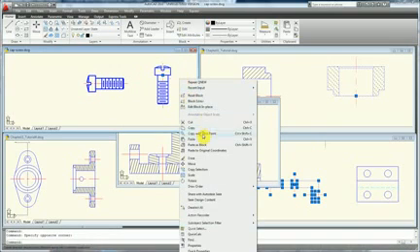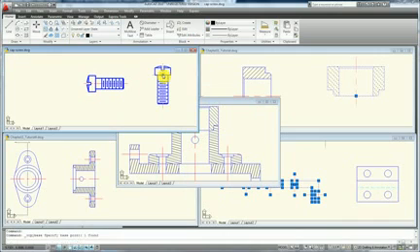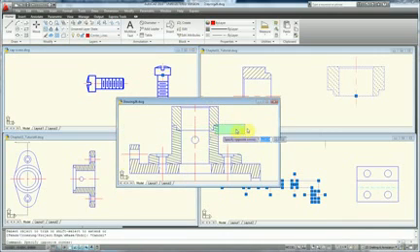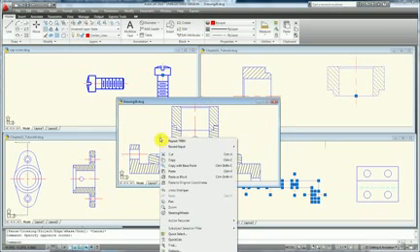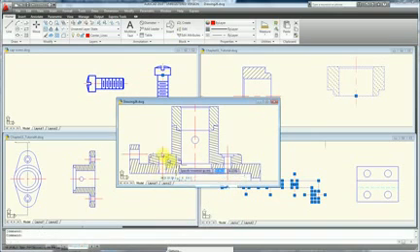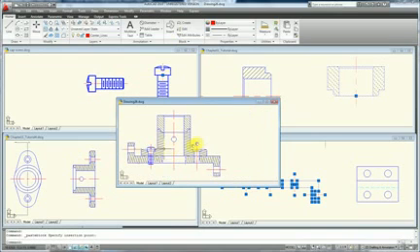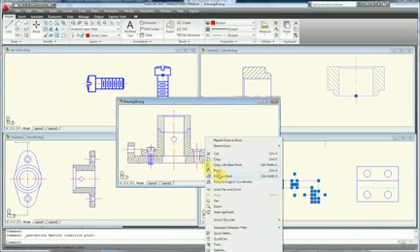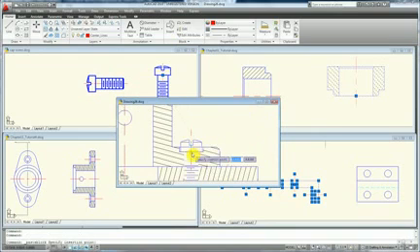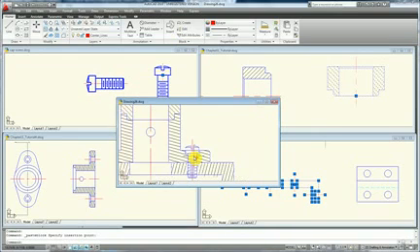We're going to choose the base point we chose earlier. Click on the assembly drawing. And now I'm going to right click and choose paste as a block. And we want to paste it about that intersection point. And we're going to simply hit paste as a block again, since we already have it as a block, and it duplicates it and places it right there.